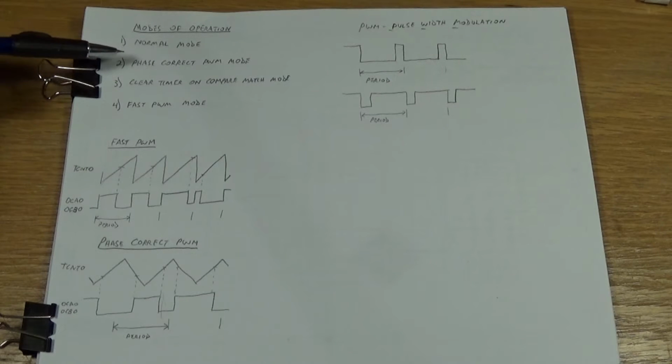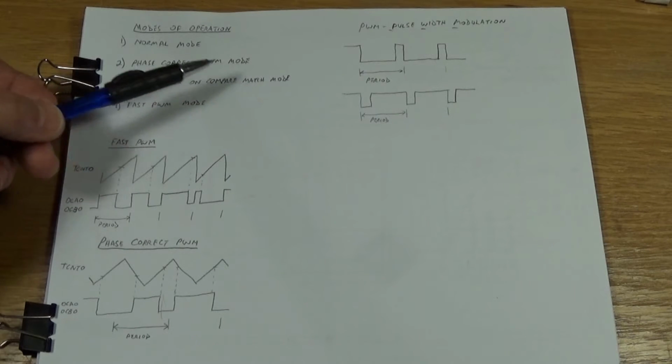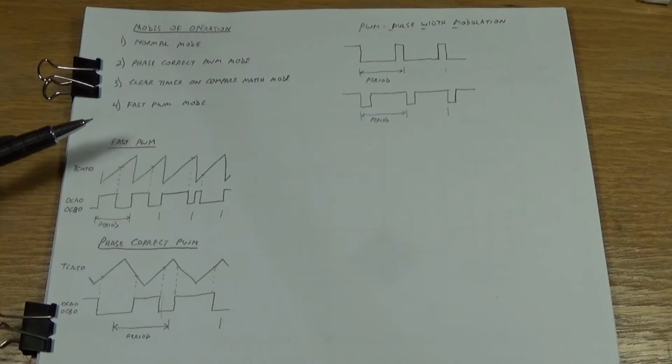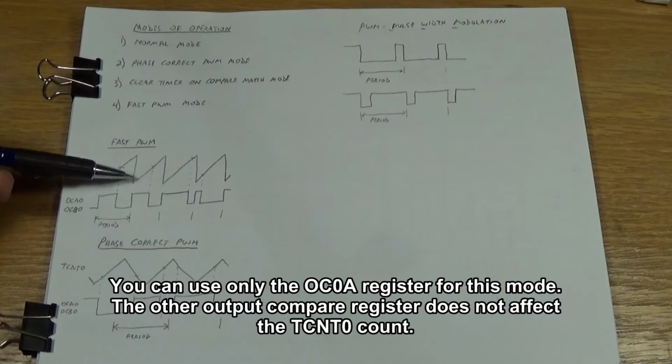Now I'm going to skip the phase correct PWM mode for a moment, and then we'll look at it in a moment here. The next mode is the one that I showed you in the previous video, which is clear timer on compare match. So in this case, the timer still increments like this, but when it hits the value of one of the output compare registers, it immediately gets cleared to 0, and then it starts up again.